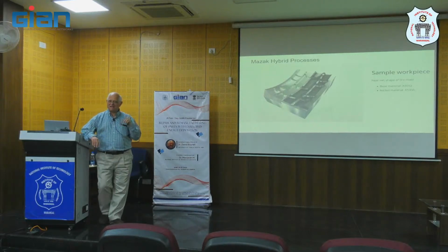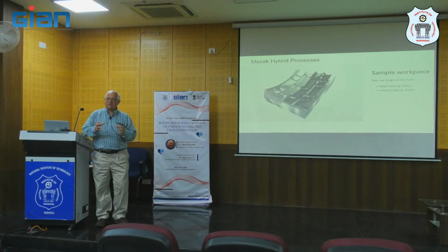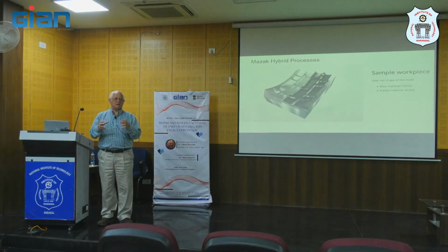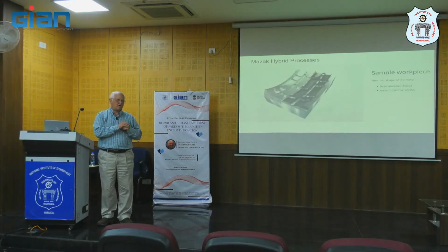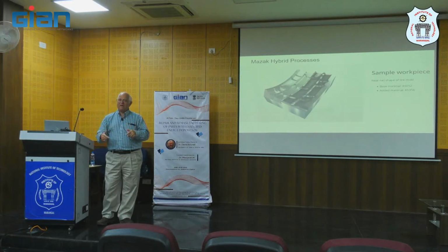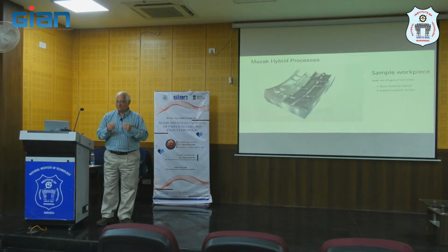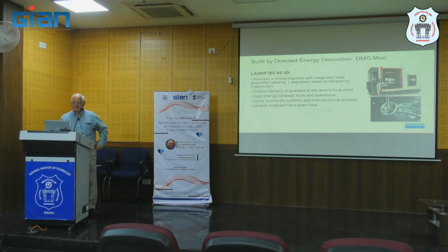And in this case, as was maybe the case with some of the others, it is a bit sequential. So they build the part and then they do the machining. But what preserves the hybrid nature here is that the part is registered in terms of where it is for both machines. So we're not taking it out, putting it in another machine, and then having to align it relative to that machine's coordinate system. Everything happens all at once. So the registration for the additive part is preserved for the machining side.